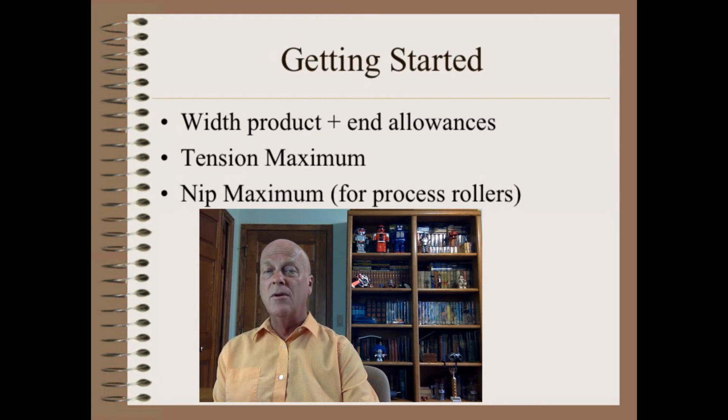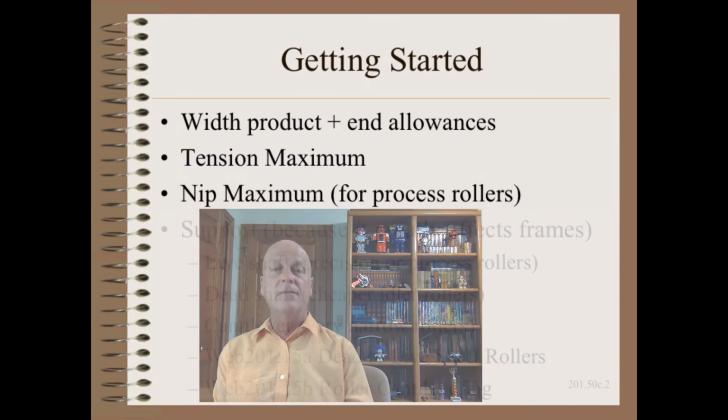For process rollers, we must take great care not to go too close to the ends with our product due to thermal gradients and the deflection-shaped nip details that we won't cover here. The working part of the roller's width needs to be quite carefully considered. Too wide and you increase machine costs. Too narrow and you increase the cost of waste and delay. Just right is, well, just right, and that depends on the details of your specific application.